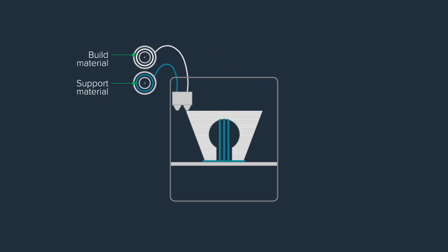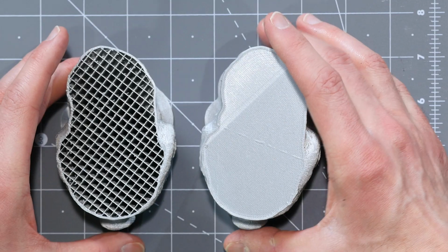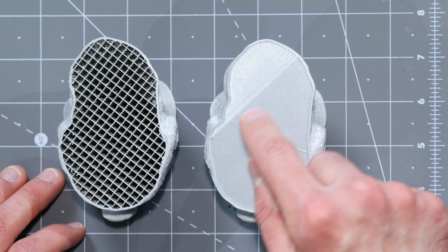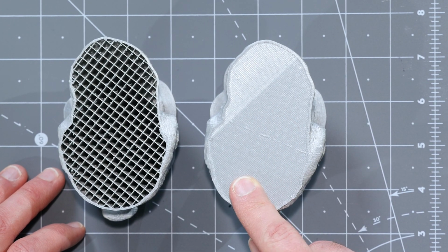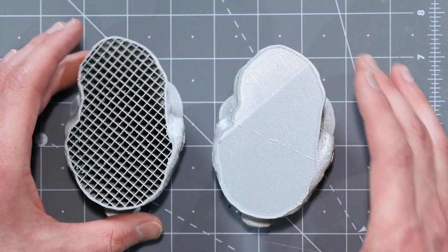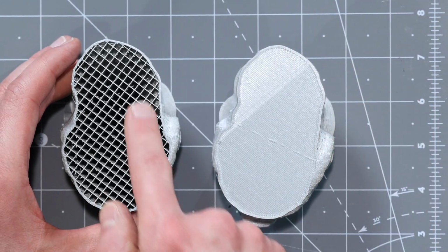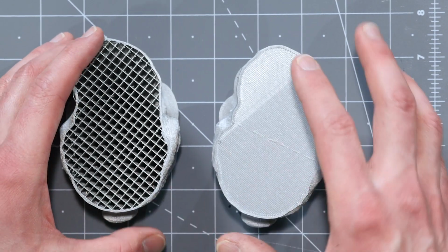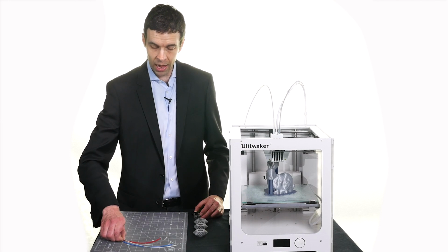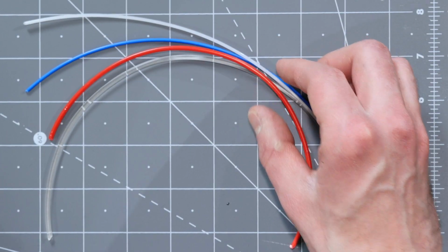And having these two nozzles that move in tandem with only one of them printing at a time enables that multi-material print. If we look at two parts that were stopped prematurely, we can remember how now the trajectory of the printhead within each layer, defined by its toolpath, defines the infill from a solid, dense, stronger part to a lighter, less dense part with this sparse rectangular infill. Filament feedstocks for extrusion AM come in a variety of materials, sizes, and colors. Here's just a few examples.